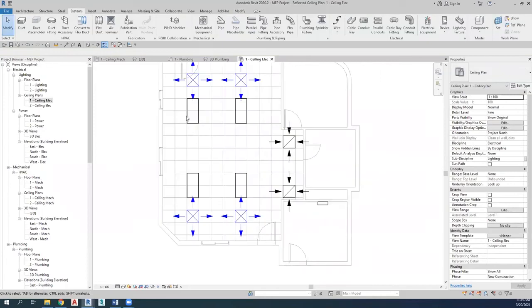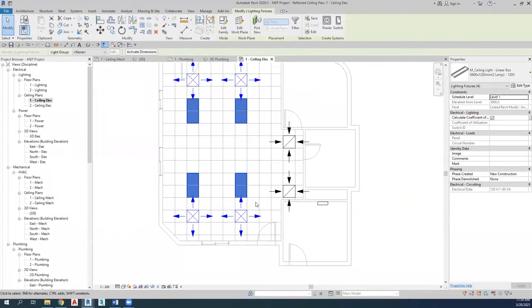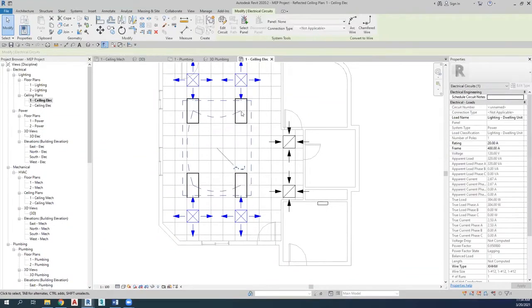What we do now is create a system for the 4 lighting fixtures, so Revit would be aware that all 4 are under one power system, connecting them all together. We then specify the panel that is responsible for providing the power, as shown, so it becomes included in the system.